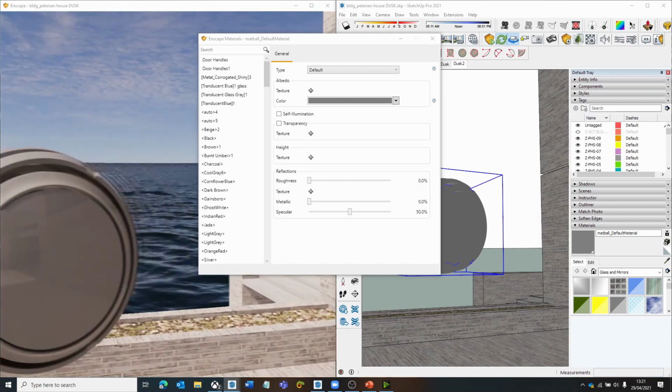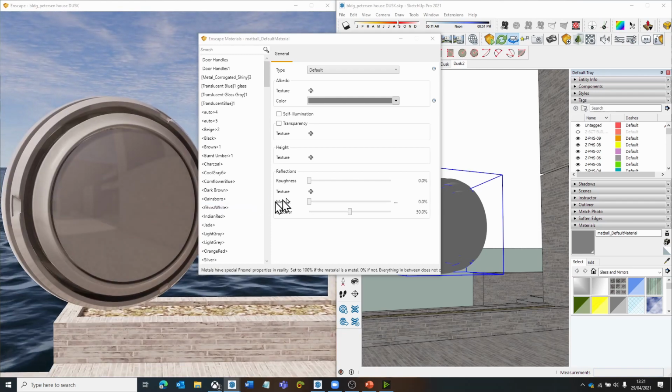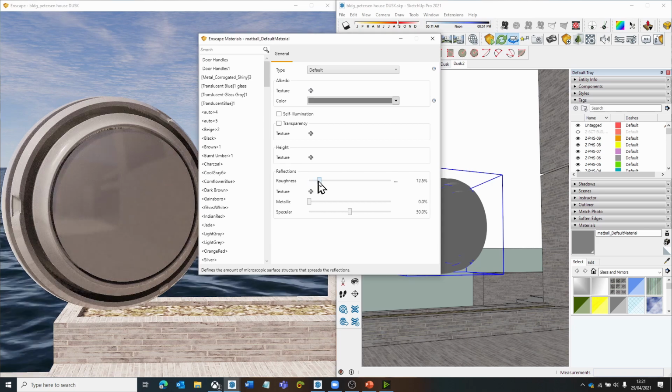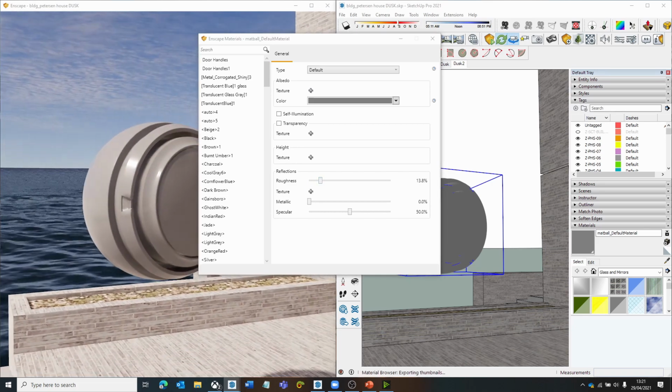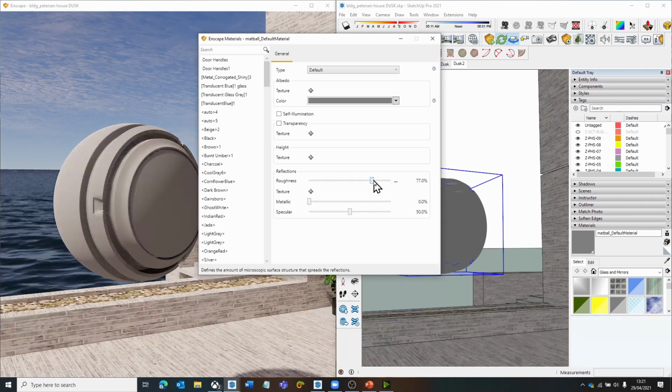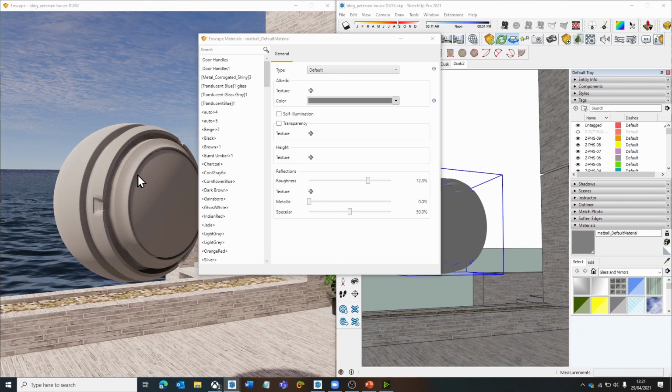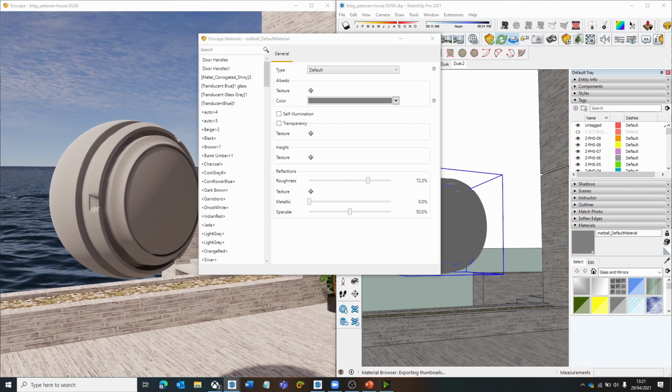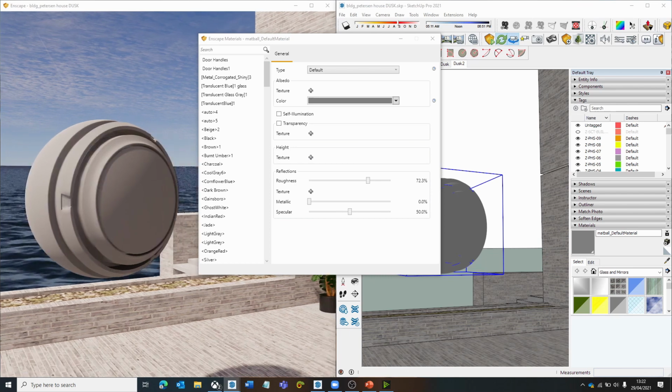And we can see Enscape is reflecting very nicely. We can essentially eyeball whether something needs to be glossier or shiny. As we said, generally I find that I need things to be under kind of 70% to make a difference. As we showed in that other screenshot previously, everything was set to 60%, and even concrete and brick will have a good degree of shininess to them.